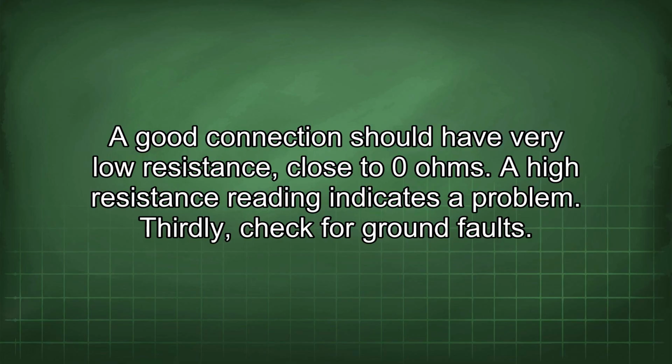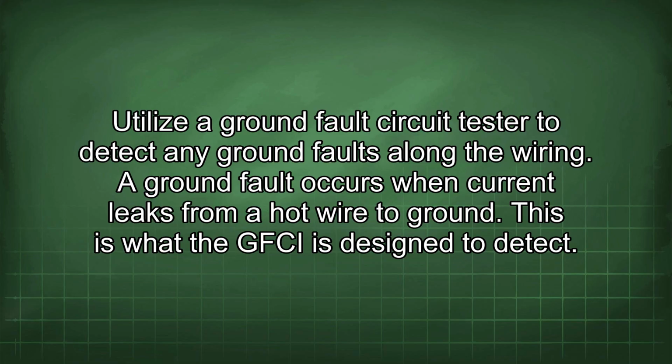Thirdly, check for ground faults. Utilize a ground fault circuit tester to detect any ground faults along the wiring. A ground fault occurs when current leaks from a hot wire to ground. This is what the GFCI is designed to detect.